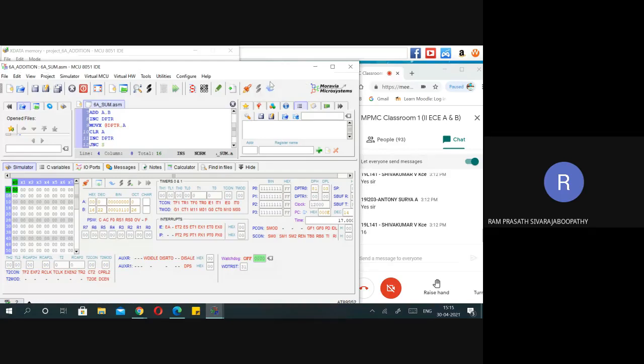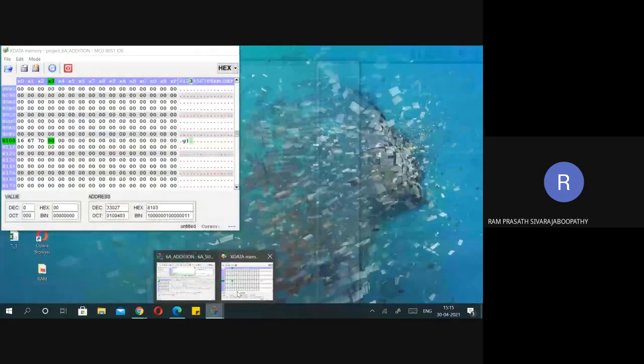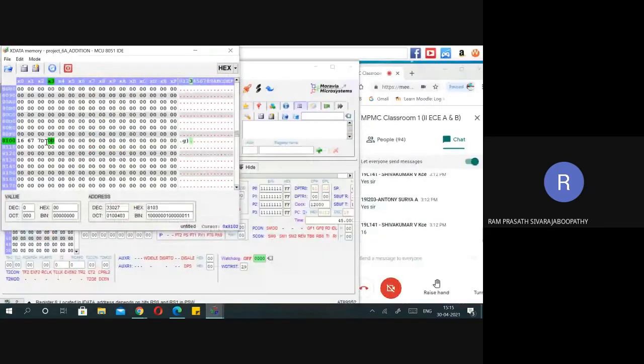Okay, sorry. Simulator, click on step. Yes. Over step up. Yes. After executing, JNC directly goes to which line? MOVX @DPTR comma A. That means it is going to store the carry also. So after that, if you execute the same line, it is executing again and again. So that's all about the result. 7D is the sum and 00, there is no carry.